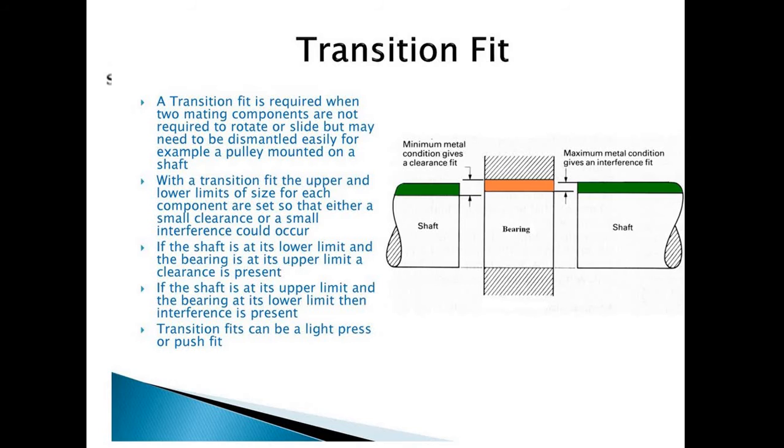Now as you can see here, in case of the transition fit, the minimum size of the shaft is always going to be less than the minimum size of the hole. It is always going to be like this. Also you can define it in another way.